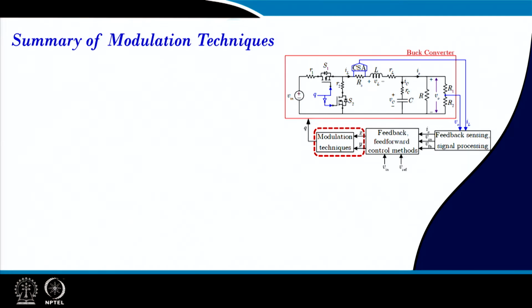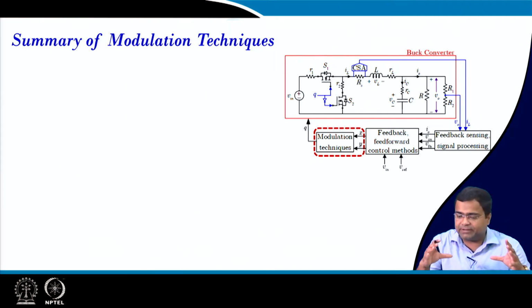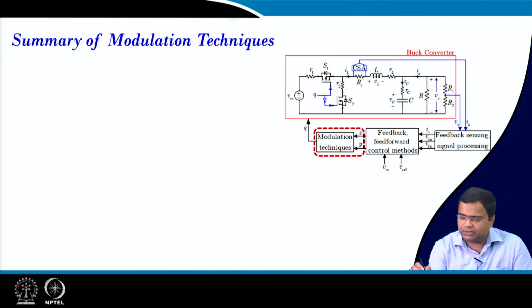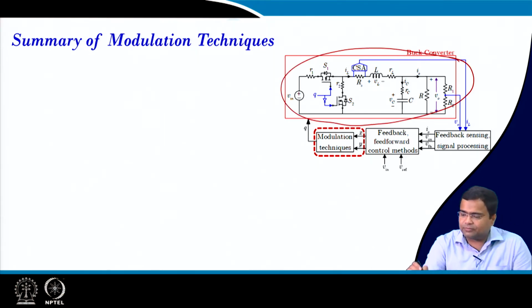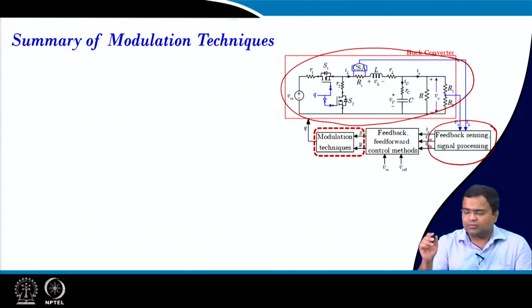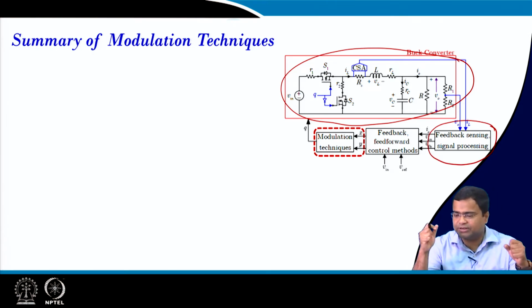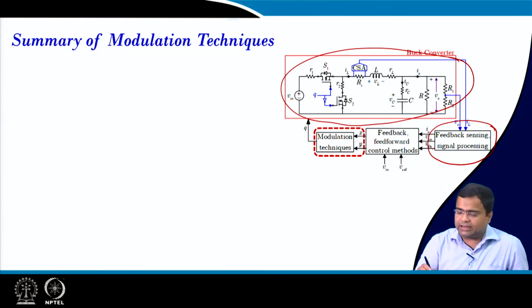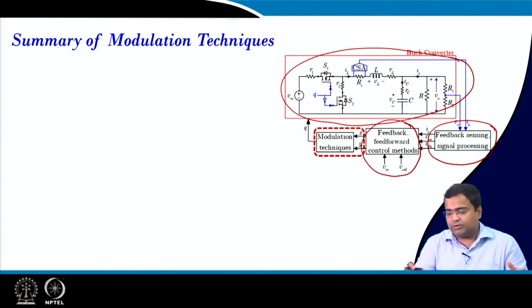So, first we want to recollect the feedback control of a buck converter. This is the diagram, where this represents the power stage, and we have this sensing circuit which will be used for stepping down the output voltage, as well as a current sense amplifier. But there are various ways of sensing current, and we may not need current feedback all the time, and then we can use various feedback control. So, depending upon the feedback architecture, we have to select the right feedback control,